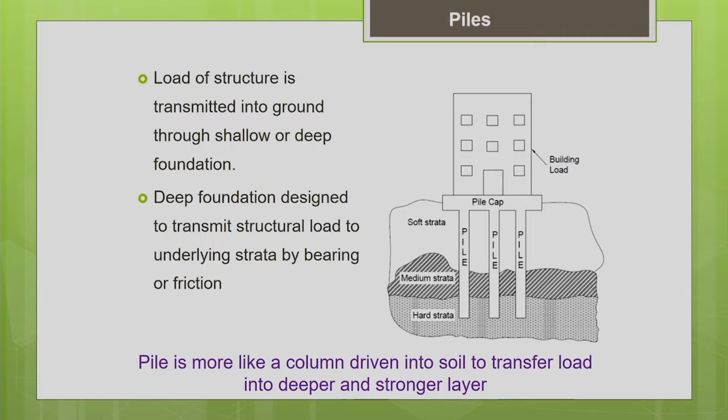As everyone knows, the load of any structure is transferred to the ground through the foundation. This foundation can be a shallow foundation or a deep foundation. Piles are examples of deep foundation. They are capable of transferring the load from the structure through a weak strata and carrying it to the depth where a hard bearing strata is available.